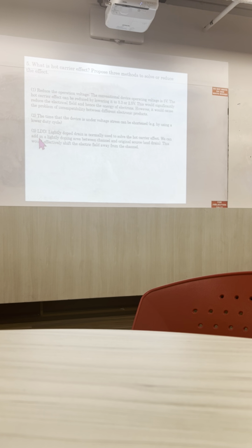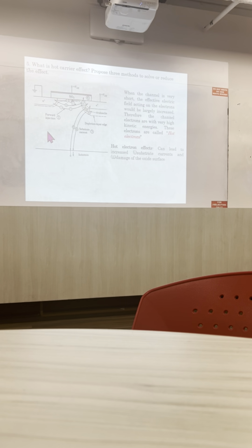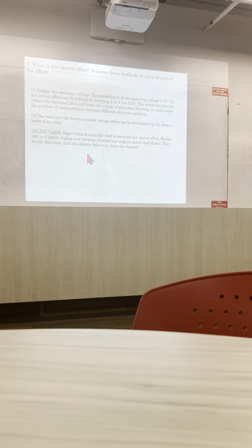The third trick is what we know about the lightly doped drain. Okay? Yes. So in yesterday's lecture, we talked about how we make the lightly doped drain, etc. Lightly doped drain essentially means we are building a N- or a lower doping concentration interface at the source and the drain location. Okay? So that N- location will essentially have high resistance, and although you are applying a plus 5 volt, not all the 5 volt falls across the channel. Okay? Some of it falls across this resistance, some of it falls across this resistance. So we are artificially eating away the voltage. It's not that great because we are heating up and things like that and more complex process flow. Right? That was the first trick that was done.